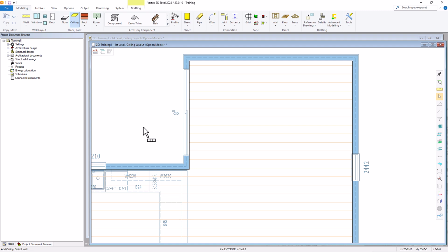I'm going to add the ceiling by adding points instead. Since we don't have walls going all the way around this room, adding points will be much easier, and we can do it in the 2D view. So we'll right click, and we want to make sure that our horizontal area by bottom plane is set. And we're going to add by using points.